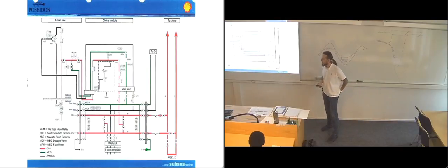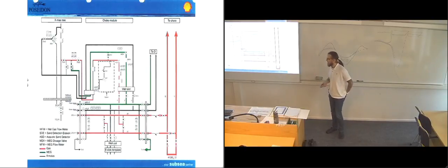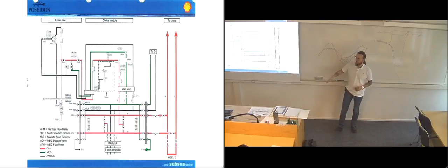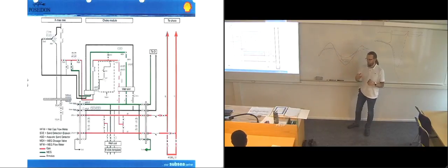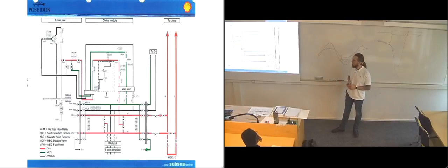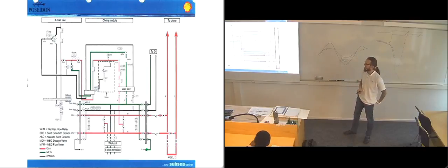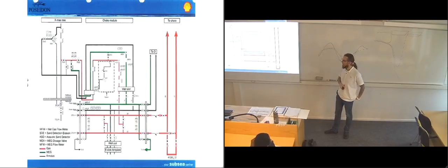So it's something you need to keep an eye on all the time in a system, really. But some fields almost don't have any problems with sand at all, because it depends on the reservoir itself. It's the structure of the reservoir which is the problem. If it's a reservoir which is very, very porous and very easily turns into sand, then it's going to follow the flow. And if it's fairly hard but porous, then it's not going to turn into sand that quickly. I think a geologist would make a better answer than I'm doing right now, but it's very individual to each reservoir, how much sand you're going to get.